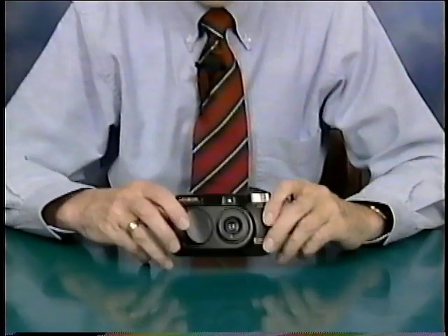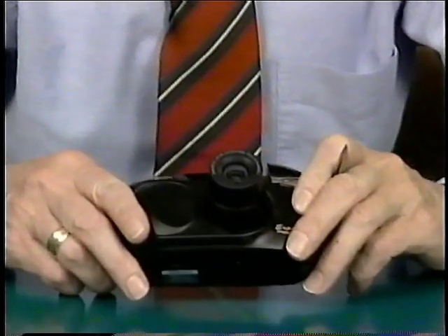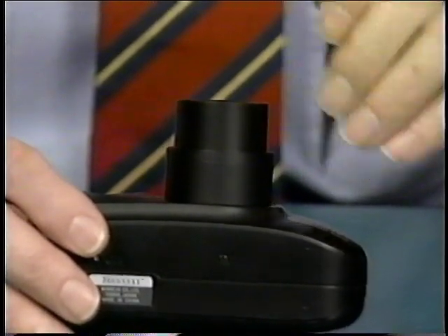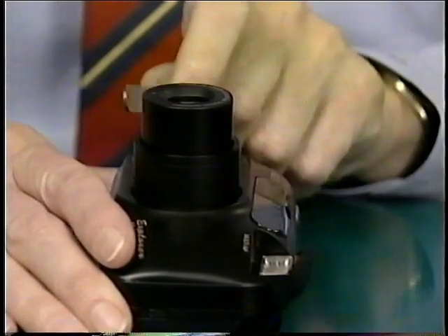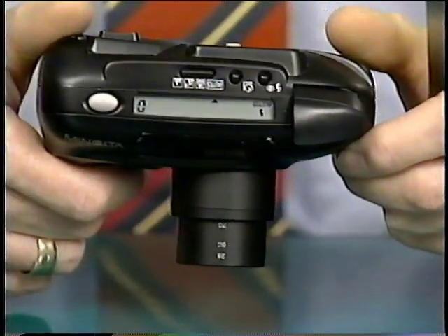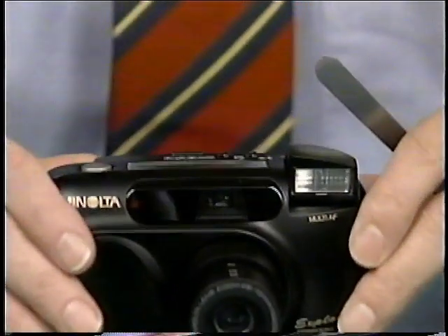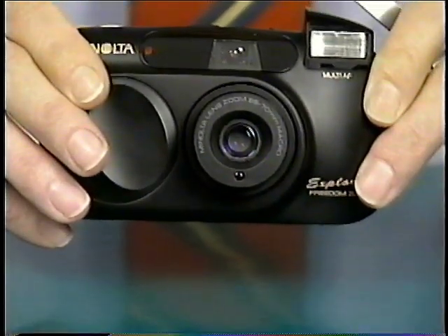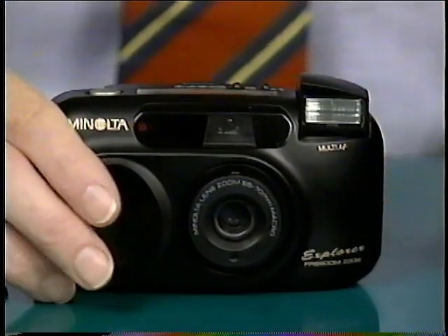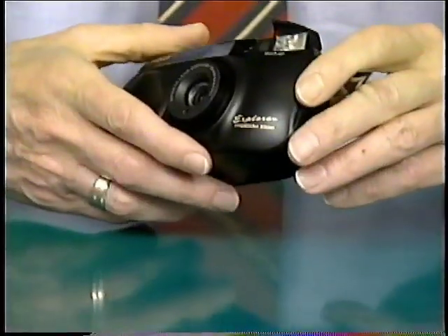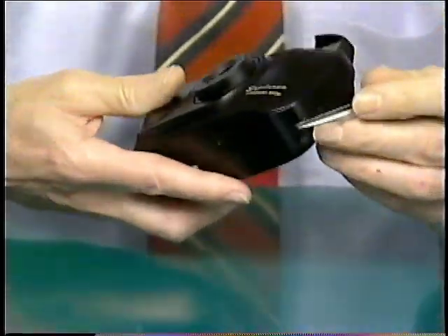When inspecting lens shutter cameras for impact damage, you use much the same method. If it's a zoom camera, zoom the lens entirely out and then again look to be sure that the lens is perpendicular to the body in both directions. In other words, it should not be leaning even a little bit one way or the other. An easy way is to look down on top of the camera just to be sure the lens comes straight out. You should also listen to the zoom to make sure, as you hear here, that the motor is steady. It doesn't start and stop or slow down and speed up during the zooming to indicate that there's strain or stress. Again, look around the corners of the body.